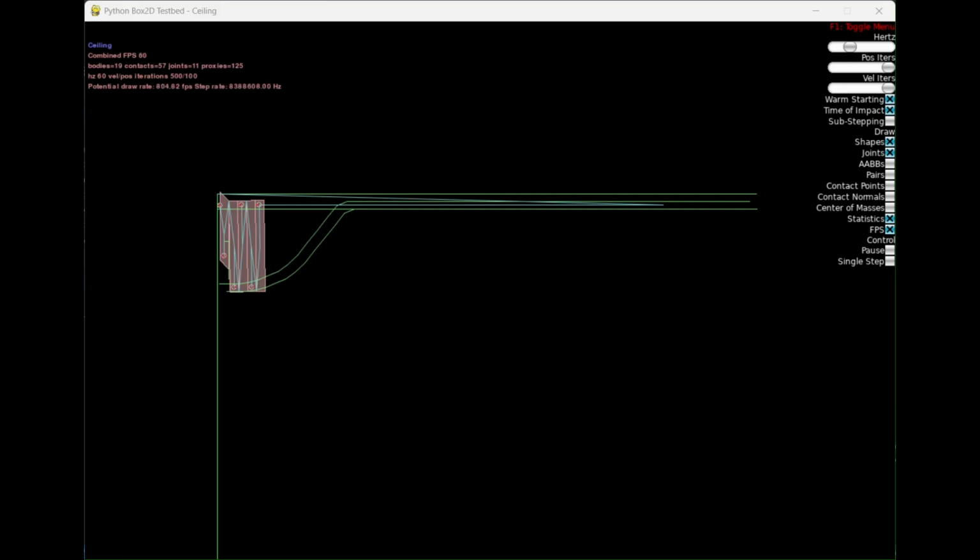We put the lower wheel of the last panel on a vertical rail so it can slide upward but not outward. It can't flatten completely, and it stops at around a 45-degree angle, but by changing the shape of those panel ends and making it a parallelogram, it can still form a gapless seal with the wall and the next panel. My wife thought the aesthetic of the angled panel would be better than that with the inset, so this design might be the all-around winner.